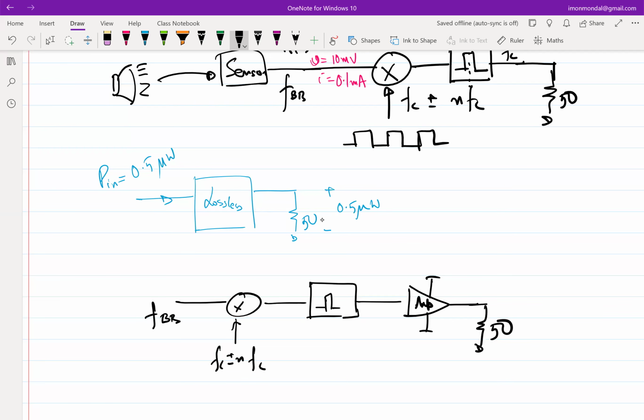What type of amplifier have you learned till now, in other courses that you have done? Common source, common drain, common gate, and so on, and differential amplifier, two-stage, multi-stage, but everything is a common source amplifier only, because that is the only stage that gives you a gain.